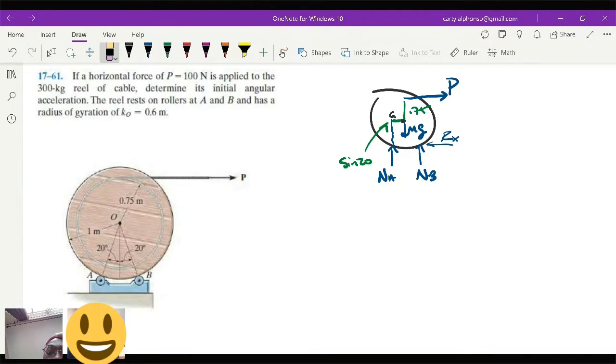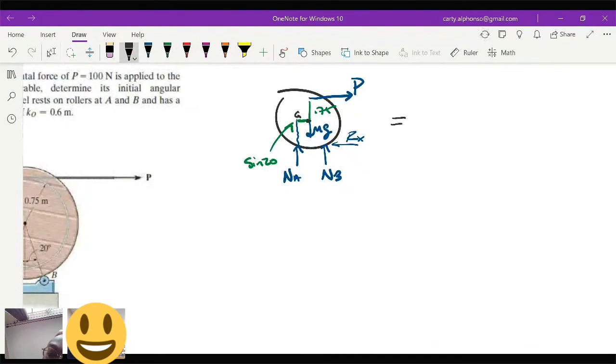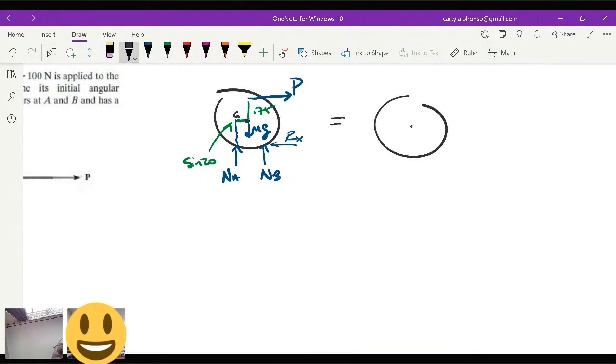So we have our free body diagram. I'm going to drop a kinetic diagram. Boom, boom. Put a circle. She normally just does MA for her kinetic diagram. That's nice, but I like to be safer than sorry. Because the thing is, you have MA and then you also have I alpha, IG. The I alpha interacts with the MA actually. And so I only ever see it when it comes down to I do know that MA equals 0. MAX and MAY both equal 0. So I do know that. But I know that there's also an I alpha that needs to be considered here.